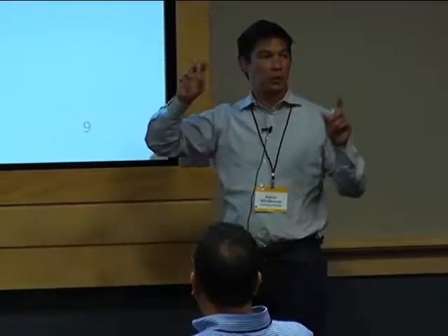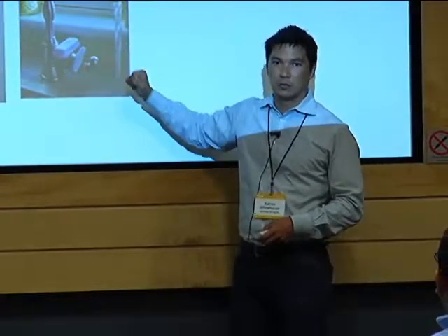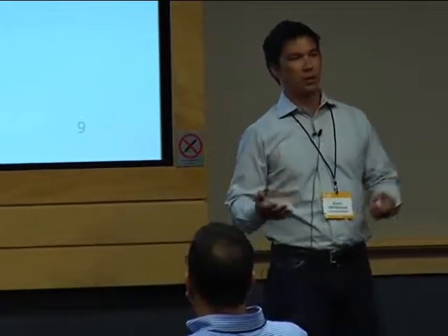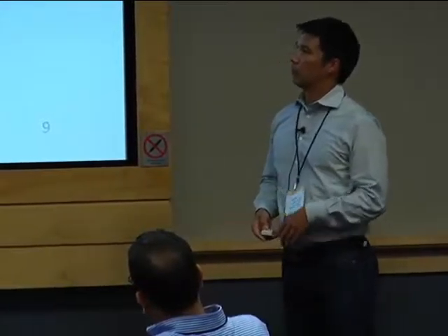We use what we call ground truth sensors, like this one here, which is a contact reed switch that detects when that handle is moved, so you know when the fixture is being used. That way we can check whether our estimates of the fixture usage are correct or wrong. And so per house, we need to monitor every light switch, every appliance, every water fixture. That's about another 100 sensors per house.